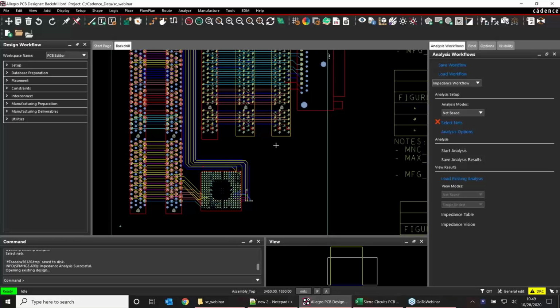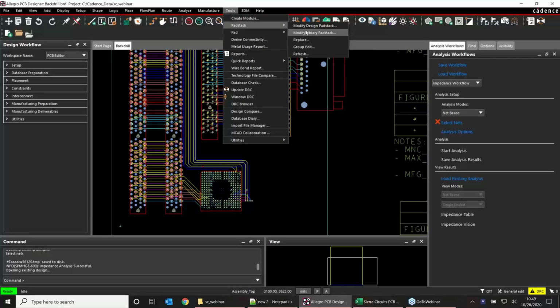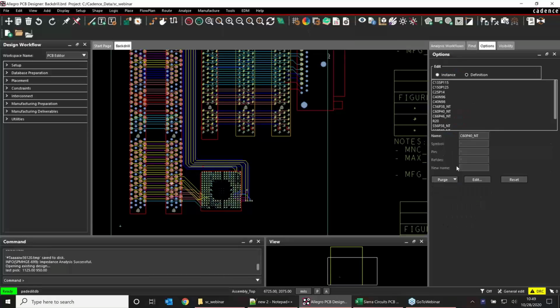The reason we want to do that is to get rid of that piece of metal that's going to be a stub on our via. So it causes signal integrity issues. We want to drill that out, just physically remove it from our board. And that's something that we're able to specify in the design tool. The way that you do that is in your padstack, you're going to say it's allowed to be back drilled, and then here you can verify what's actually happening in that padstack.